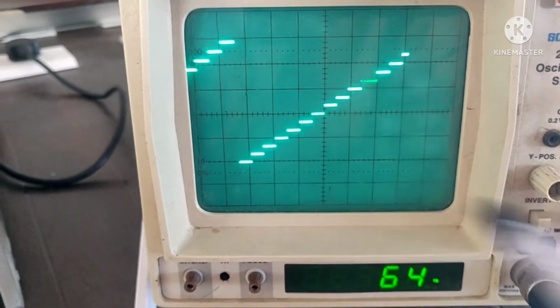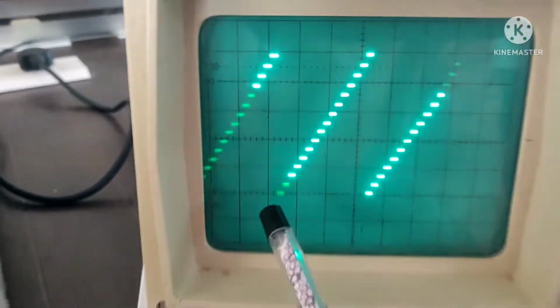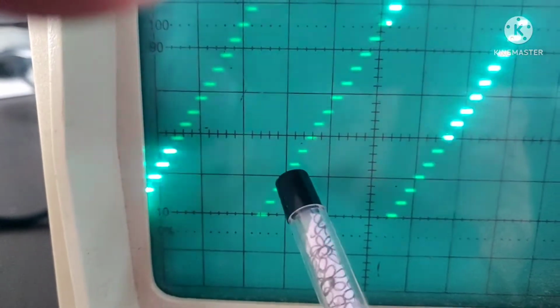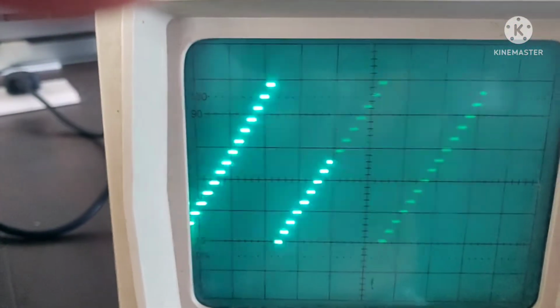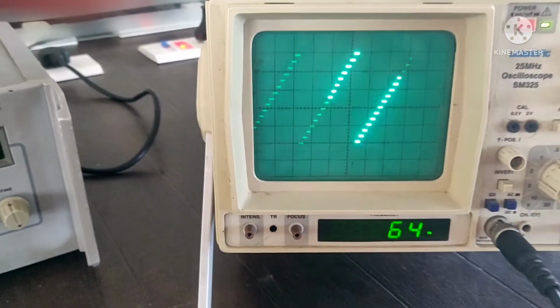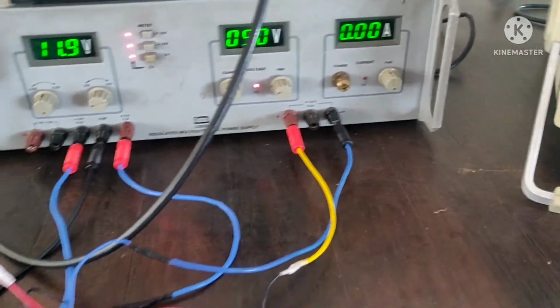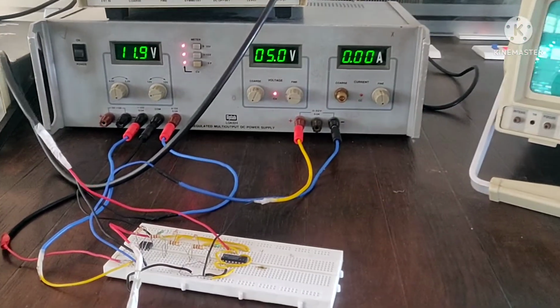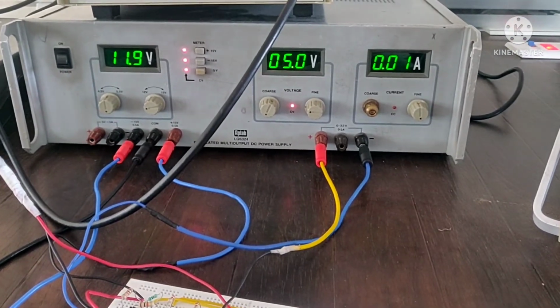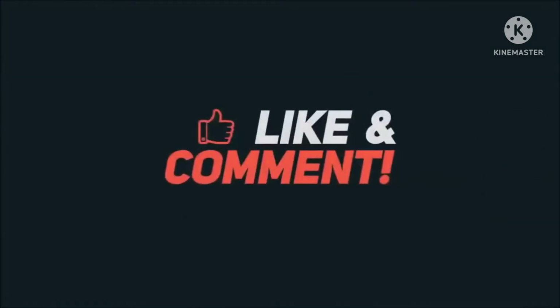Here you have to measure the full scale step size and each step size by multiplying with the volts per division, and you can calculate the resolution of the waveform. Monitor here the whole assembly of the power supply, CRO and all those things like this. I think it will help you. Try it. All the best.